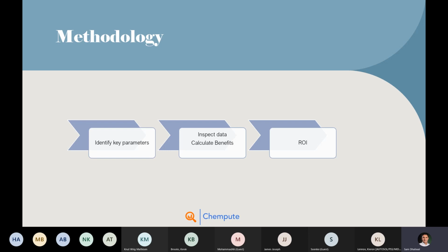You also want to look at product qualities in the sense of impurities that are allowed in a more valuable product, and I'll touch on that a little bit more. So really the idea is to identify about 2 to 4 of these parameters and extract and review data for about 1 year for those parameters. And by review, I mean doing some statistical analysis on that data.